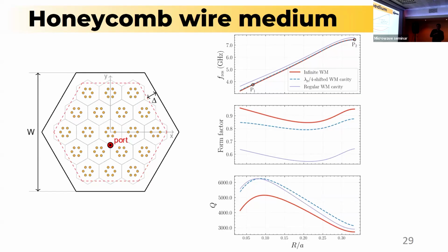In this case, we have identified that in the cavities the quality factors look kind of similar. They are not changing dramatically, indicating that the power stored is kind of similar when we compare it with the power dissipated. The two sources of power dissipation are the currents in the wires and the currents in the cavity walls. It looks like this ratio between energy stored and energy dissipated is kind of similar for the cavities. Okay, thank you. My pleasure.